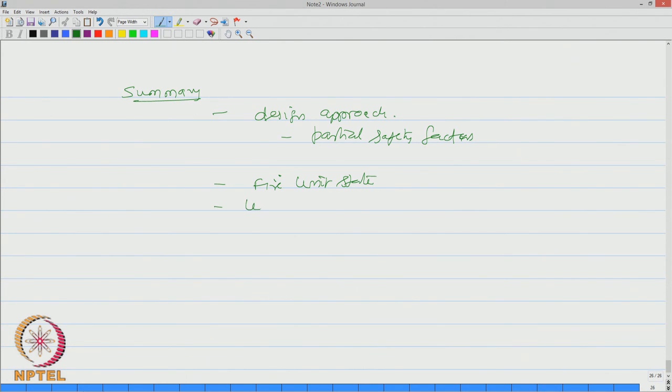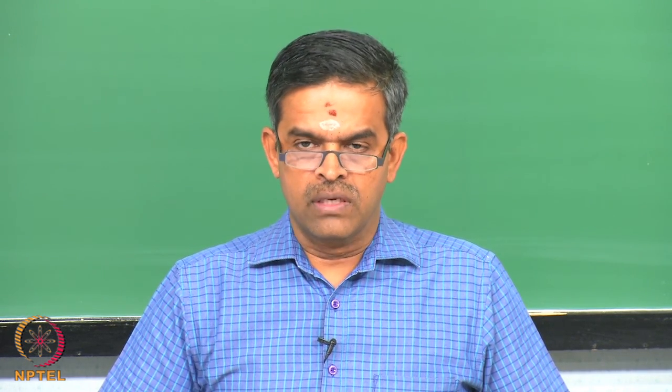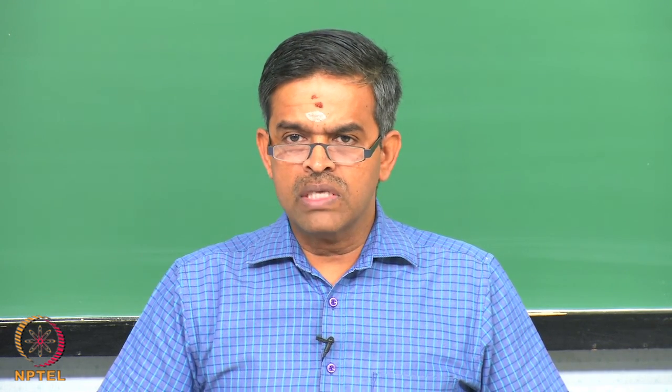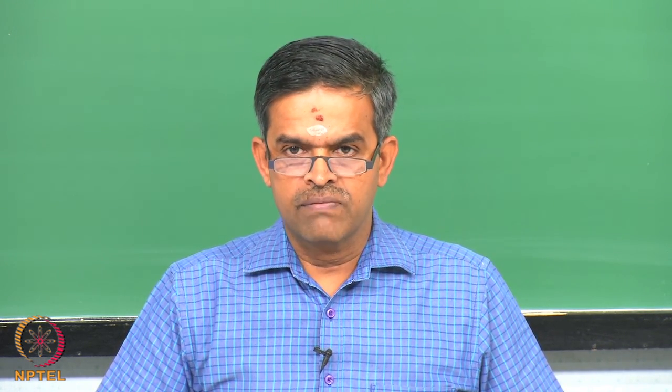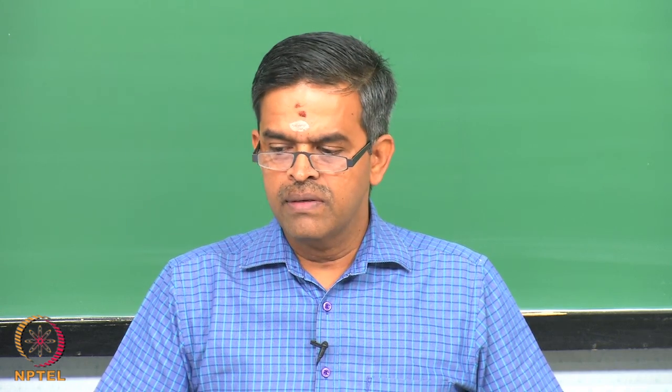We discussed the linearization of the stress strain behavior of steel at elevated temperature, and we realized that the governing equations used in compromising the Young's modulus reduction and yield strength reduction by appropriately choosing either method A or method B give you conservative statements when you compare this with the real stress strain behavior of steel at 550 degree centigrade.